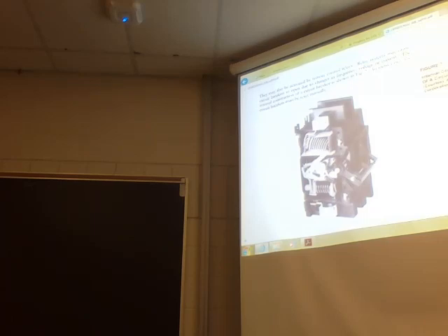The internal construction of a circuit breaker is shown here. This is a residential type breaker. In most cases, the circuit breakers must be reset manually. So if that breaker trips for an overcurrent or a short circuit, it will go to a position between on and off. And usually, if it is tripped, the switch has to be switched all the way to the off position and then back to the on position.